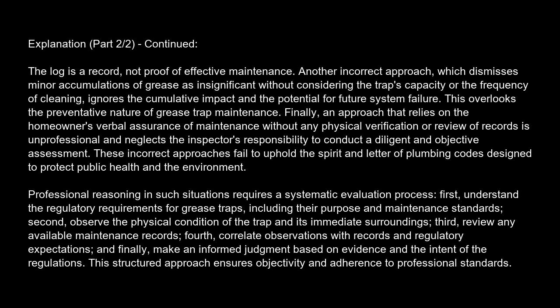First, understand the regulatory requirements for grease traps, including their purpose and maintenance standards. Second, observe the physical condition of the trap and its immediate surroundings. Third, review any available maintenance records. Fourth, correlate observations with records and regulatory expectations. And finally, make an informed judgment based on evidence and the intent of the regulations. This structured approach ensures objectivity and adherence to professional standards.